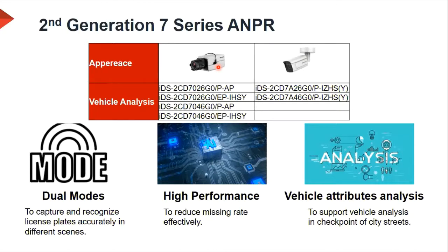That's probably the most important thing when it comes to ANPR. If you go over 30 degrees, the font in the camera's view changes so much on the number plate that it makes it not recognizable. The characters will move closer to each other the more angle you've got on the number plate, and the font sizes and those kinds of things also play a big role. So please stick within these specifications, and you'll have very high success rates on these cameras.